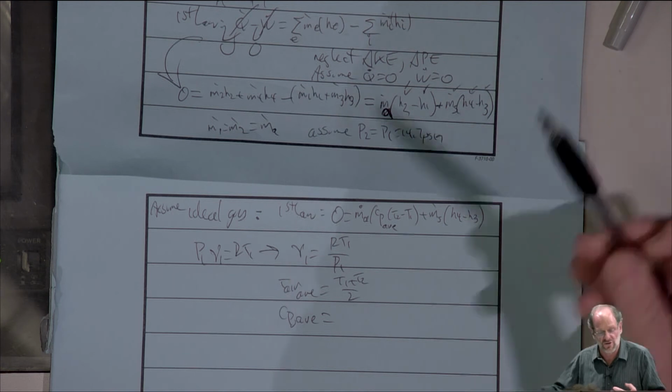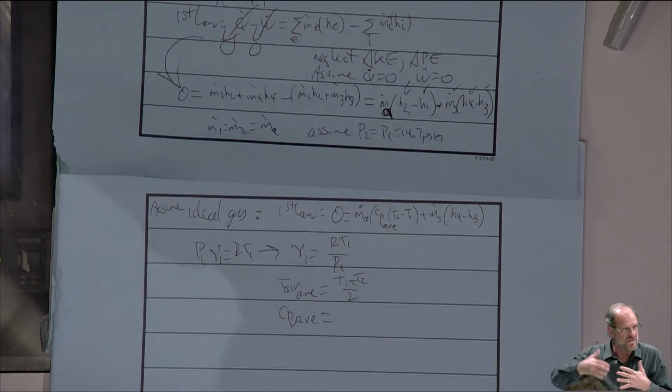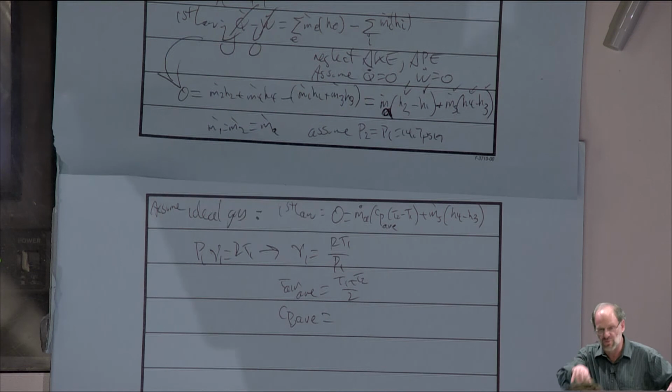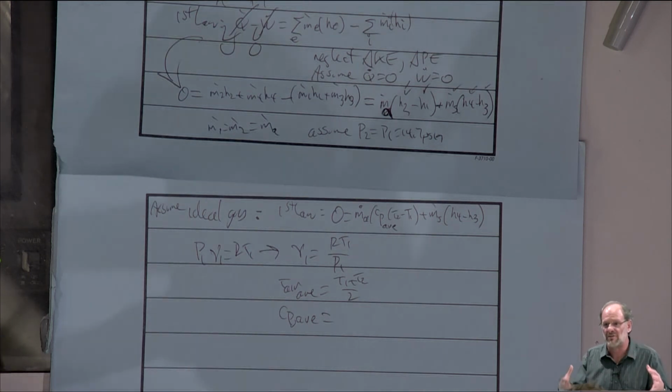I mean, sure, you're talking about a heat exchanger, which is largely just open space. How can you really have a big pressure difference between one end and the other end? Take a big box. Is the pressure on the left side of the box different than the pressure at the right side of the box? No, it's just one big volume, right? And that's kind of how heat exchangers work. They're just one big volume where you've got some tubes passing through. There may be a slight pressure drop, but not that significant. Certainly we're going to be able to ignore it.